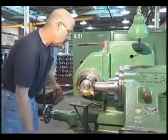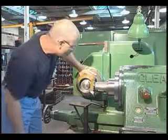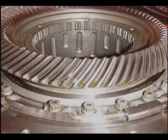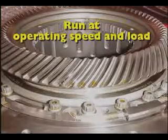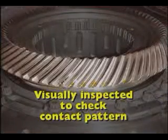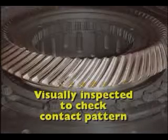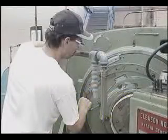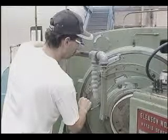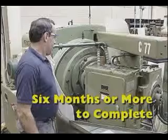But how will the gear perform under load in a gearbox, and what will the contact pattern look like then? This leads to more steps in the trial and error process. First, the gears must be mounted in the gearbox and run at operating speed and load. Then the gears are visually inspected to check the contact pattern, which is indicated by the wear pattern on the mating tooth surfaces. If the pattern is not correct, which is commonly the case, it's back to the tooth cutting and grinding machines, where settings changes must be made, new gears must be produced, and the cycle continues. For a new gear design, this process can take up to 6 months or more to complete.